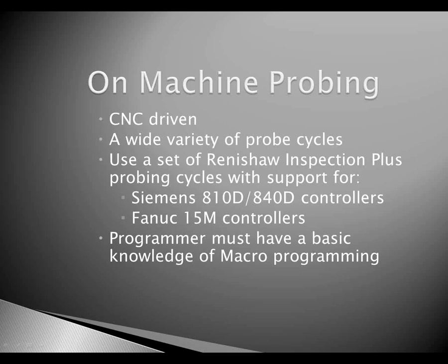NX uses standard Renishaw probe cycles for either Siemens 810D or 840D controllers or the Fanuc 15M controllers. And output variables from the probe will vary from machine tool to machine tool and controller to controller, and the programmer will have to know how to build the logic to manipulate the output. In other words, the programmer must have a basic knowledge of macro programming.